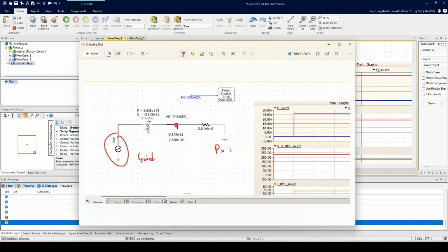is 300 megawatts, okay? And it would just say, hey, my Q, and they may also say, my power factor is about, just to keep things easy, power factor is 0.95. So what that means essentially is that they've got a bit of a reactive component. So let's say Q is equal to,